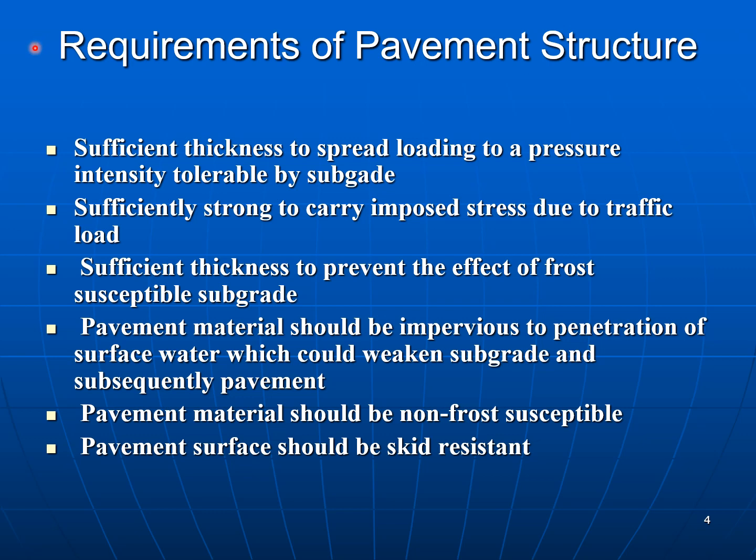Requirements of pavement structure: sufficient thickness to spread loading to a pressure intensity tolerable by subgrade, sufficiently strong to carry imposed stress due to traffic load, sufficient thickness to prevent the effect of frost-susceptible subgrade. Pavement material should be impervious to penetration of surface water, which could weaken subgrade and subsequently pavement.